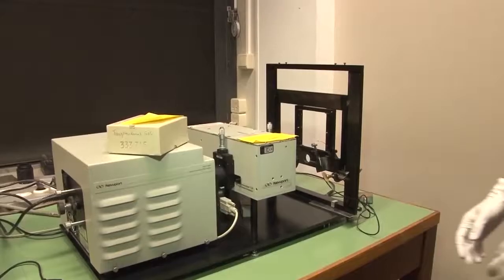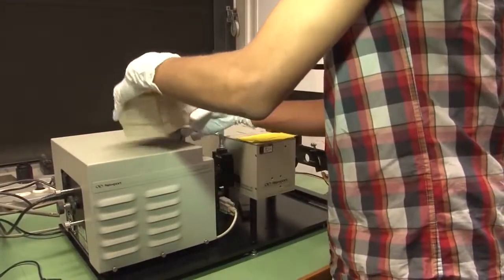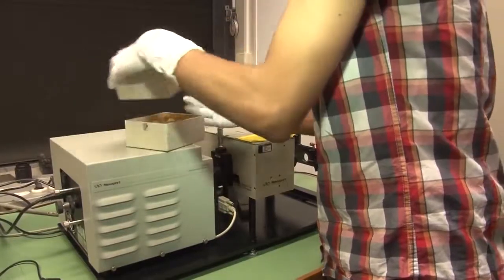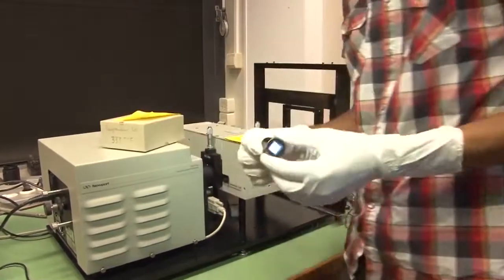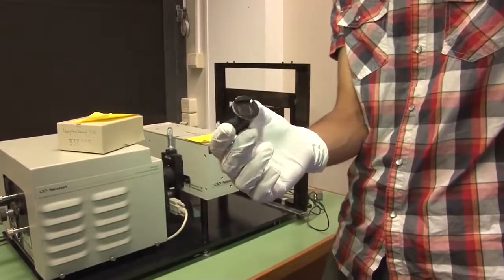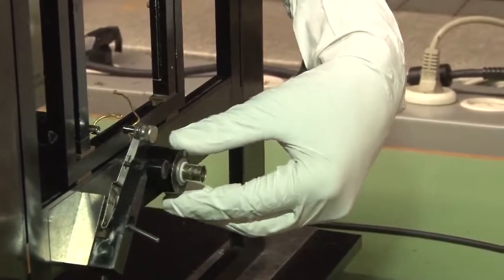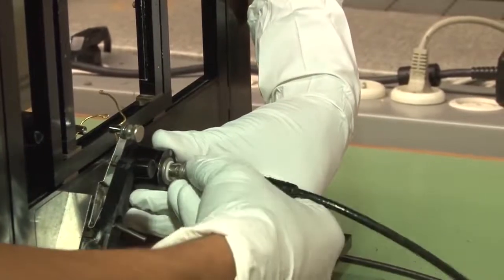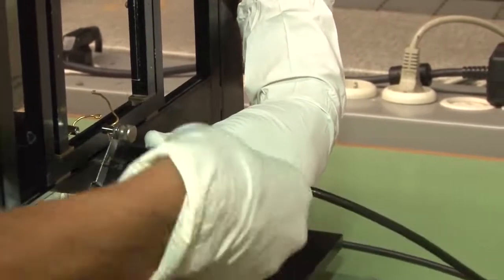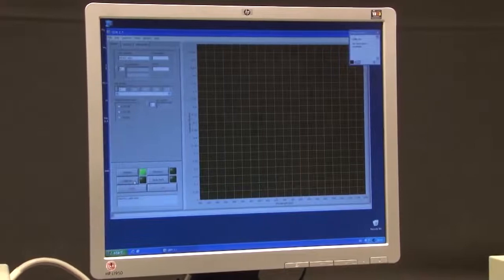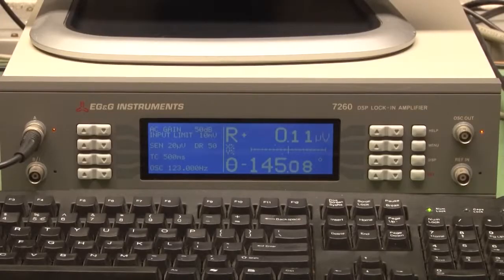We are going to measure a solar cell. This means we first have to calibrate our light source. For that, we use a calibrated silicon photodiode. This means that we can translate very accurately the light-induced currents in the photodiode to the number of photons. The photodiode signal is measured as a function of the wavelength.